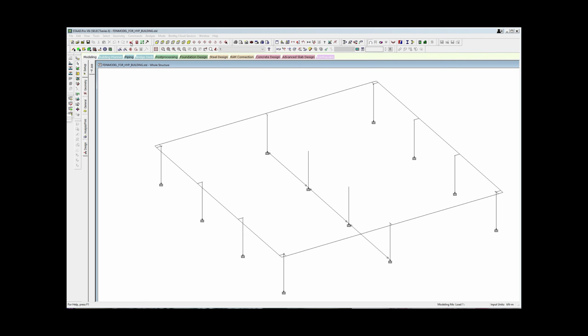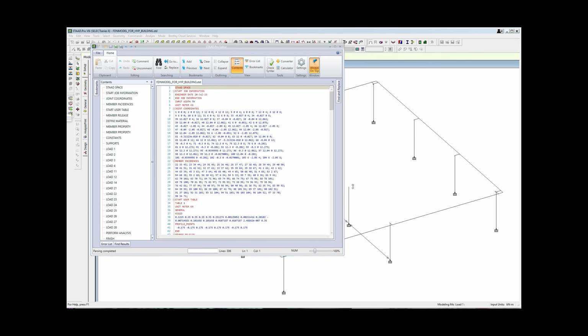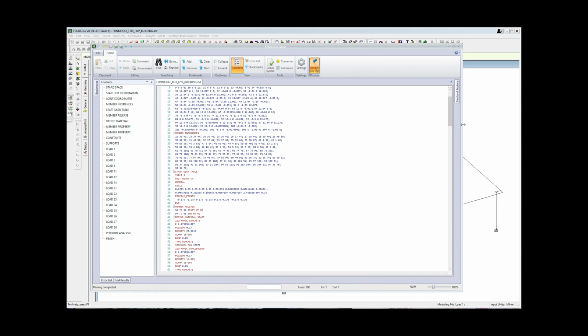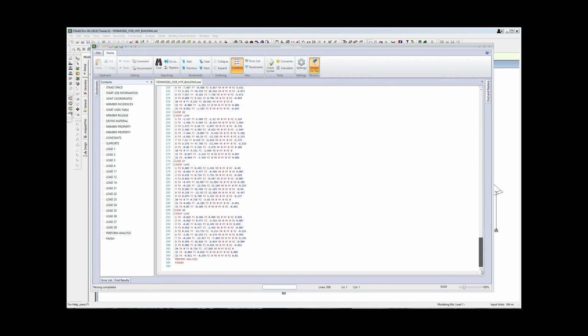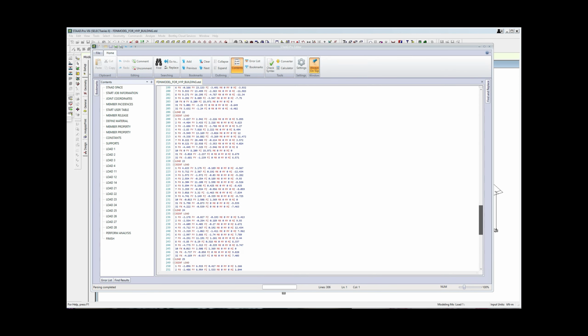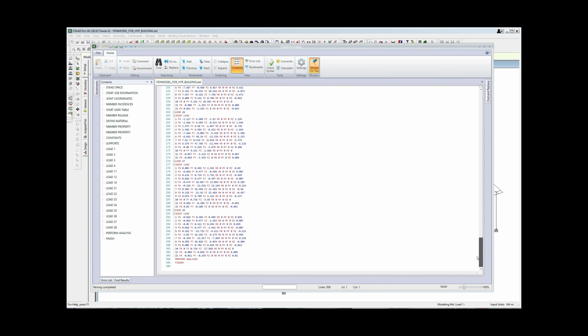So to define load combinations, it is nothing but the same load combinations as for limit state design. So we have only the primary load cases. It will have the same load cases and same load combinations as we use for steel design, except one of the load combinations in which we have a 0.6 factor for lateral load.